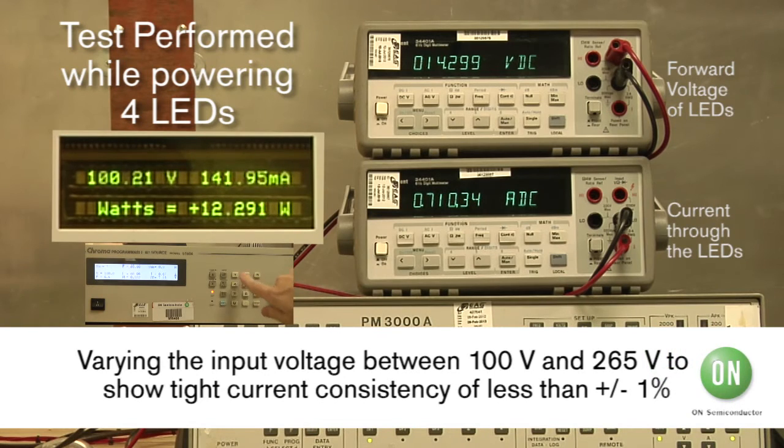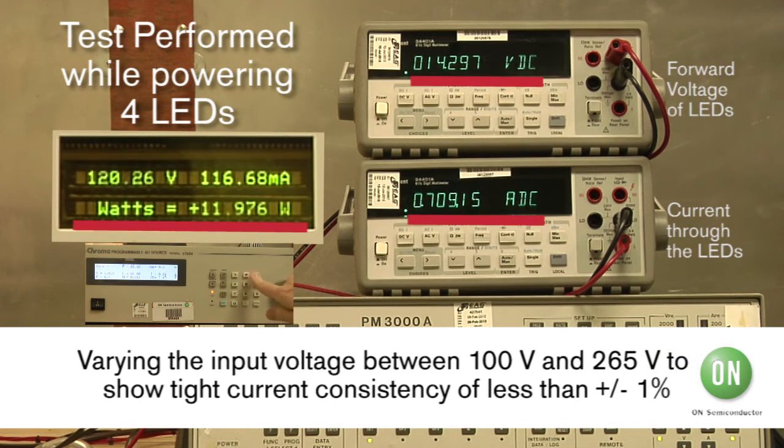We first performed the test while powering only 3 LEDs and increased the number of LEDs to 4 while sweeping the input voltage, illustrating tight current consistency of less than plus or minus 1%, taking into account all the forward voltage variation of the LEDs.